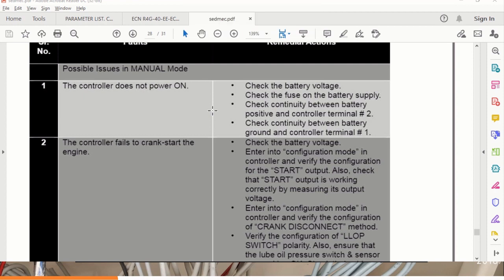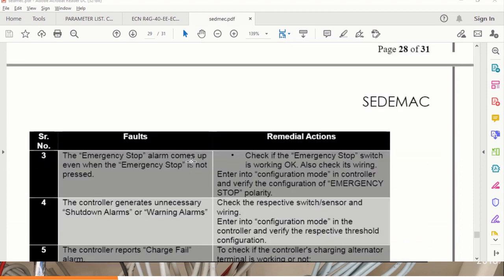So other than the DG battery and self starter, there is a configuration issue inside the controller that we can also verify. But if the engine was running already before without any issue, then normally setting related issues are very minor. Roughly these are the only issues: the self starter connection is loose, the DG battery connection is loose, the DG battery is flat, or the self starter winding is burnt. This could be the probable reason that it is not taking a proper crank. So this is what the person has to check.